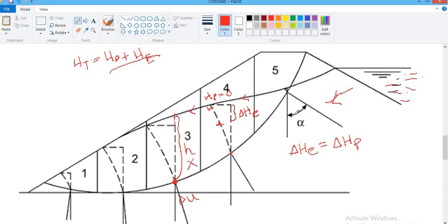This we have actually discussed in your second year under soil permeability, and also in flow nets. Just to remind you what we are doing here, taking this water height is not correct. What we have to do is draw the flow line, draw the equipotential to the flow line, and then find that vertical height. Let's say this vertical height is HW.